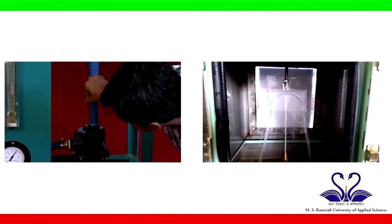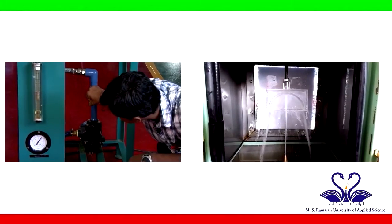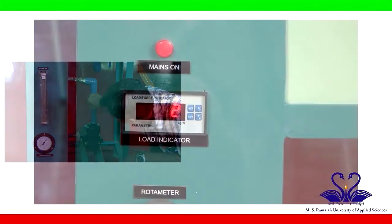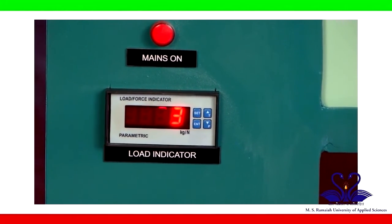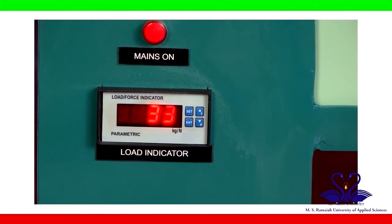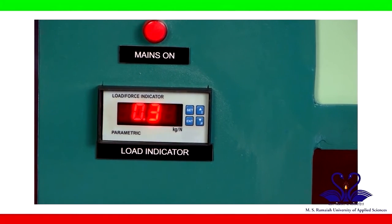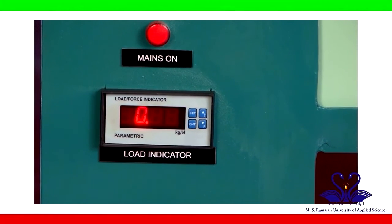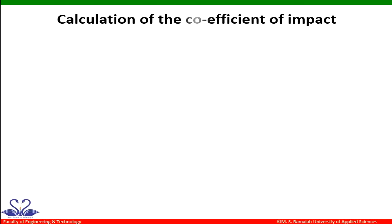I have set the flow rate at 15 liters per minute and the fluid is exerting a force on the vane. This scale is showing a value of 0.33 kgs. So this is the force of impact of the fluid that is being exerted on the hemispherical vane. Let us calculate the coefficient of impact.